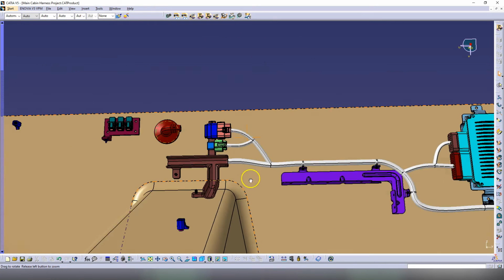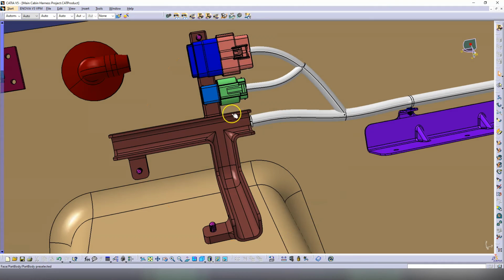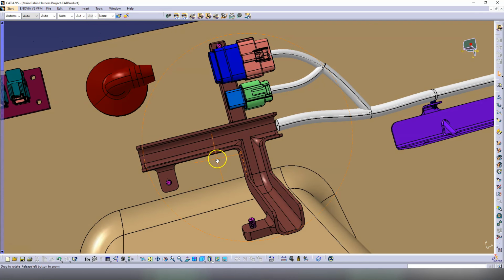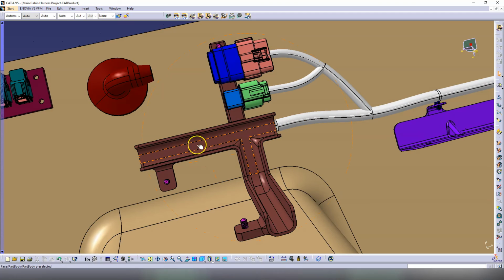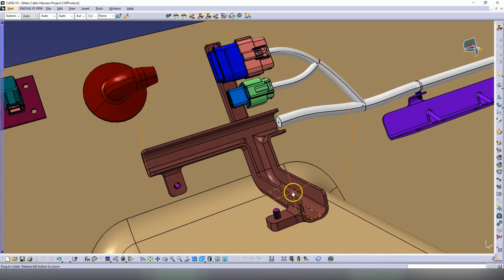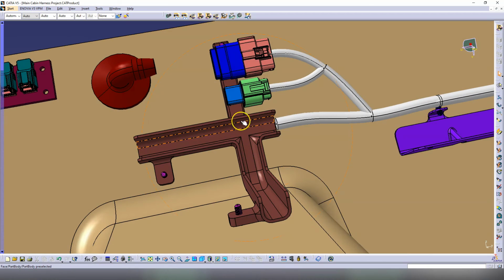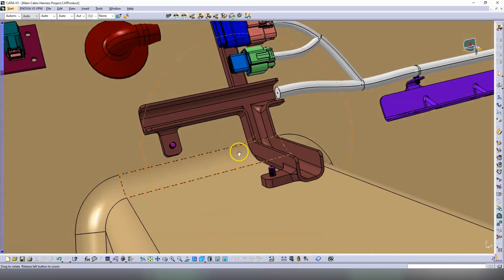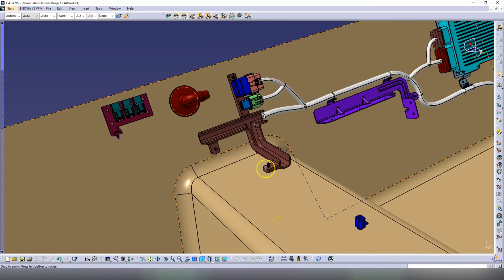Okay. Fine. So from here, we do not design bundles in plastic channels. If you work for a company and they tell you to design it, you just do it. You don't have to say no. But if they leave that decision to you, I personally do not design bundles inside plastic channels because it's not needed. I just make measurements of the plastic channels and I make sure that all the wires fit inside the plastic channel. This is everything that matters.